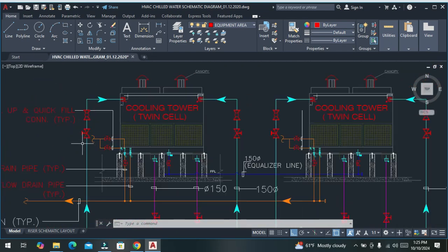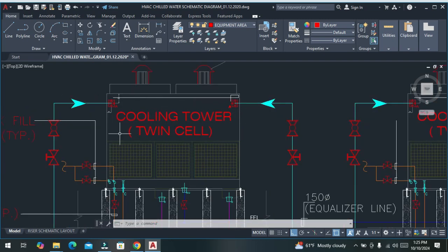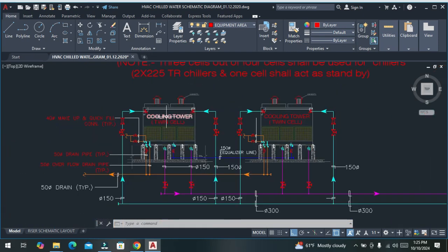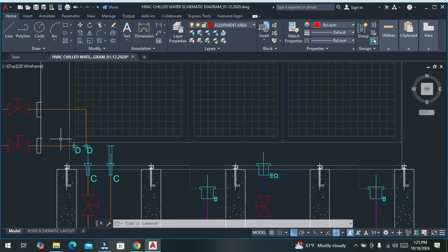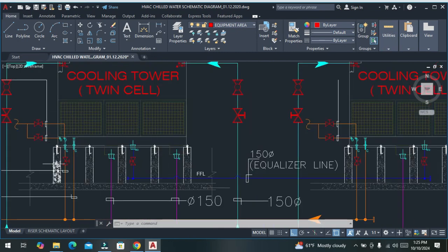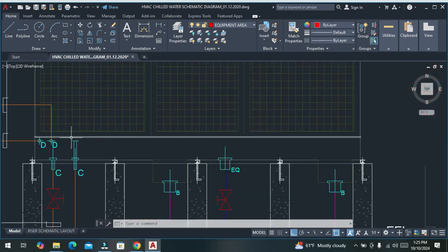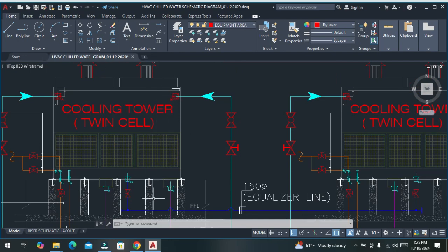Okay, hot water enters from the top, sprays like this, goes to the fins, and the fins split the water and spray it downward. During this process the water gets cooled and falls into the catchment area, which is the foundation where this cooling tower is installed.